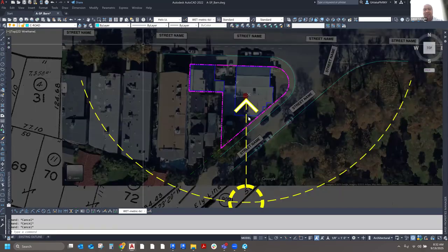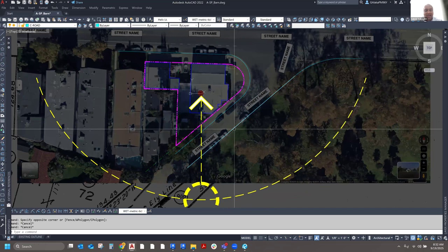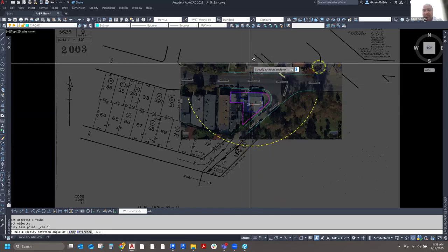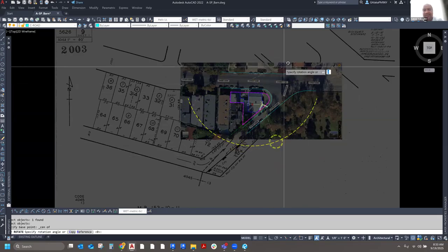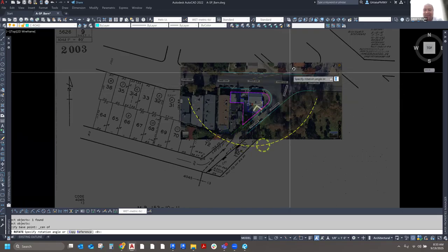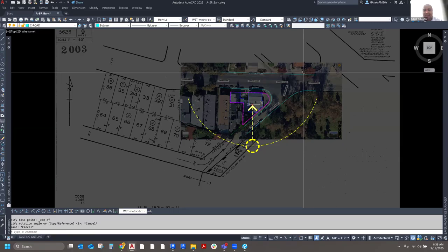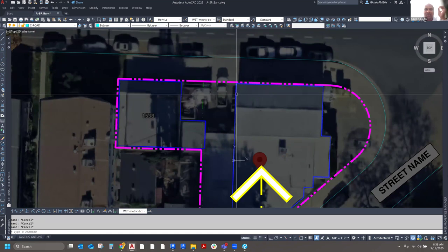So using those two, I've created a very, very rough site context drawing. And again, it's very important to have this oriented north, because as an architect you need to know that the sun does this every single day. It starts in the east and then sets in the west, which means that this part of your building gets the most sun. So if you're going to put solar panels or whatever, it's important to know which way is true north. Because in Revit, I'll show you later, your site plan is always in true north, but your architectural plans are always going to be orthogonal.